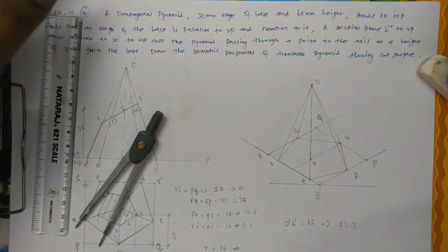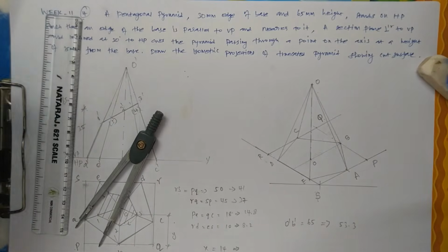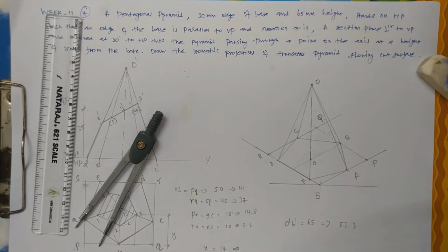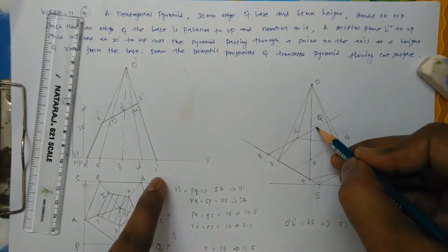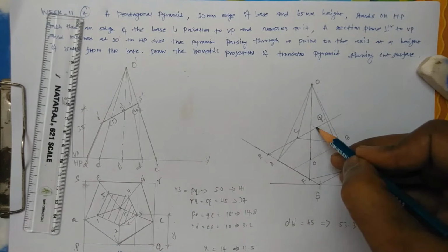Okay, like that we have to find all the points, then erect a vertical line that will meet the strips. Actually, we have not measured anything from the vertical plane, because when you are making the vertical plane, it is not a true length, it is apparent length only. So we erect a horizontal line, we mark the sectional things on the horizontal plane, and we measure as X and Y to identify the point in the horizontal plane.